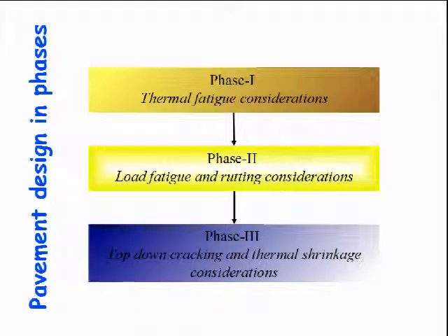And in the third phase, the top-down cracking and thermal shrinkage may or may not be related. For example, we did some study on thermal fatigue. We found that they are related to the thickness, but not very strongly. So if you agree that top-down cracking and thermal shrinkage considerations are related to some extent to the thickness, but not very strongly, then place them as phase 3 of the design, where you are looking at the mix side, as well as checking whether the thickness provided primarily due to fatigue and rutting is safe enough to consider the top-down cracking and the thermal shrinkage.